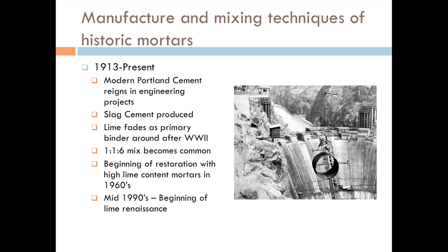So as we started moving forward, Portland cement, like I said, reigns in engineering projects. That's a photograph of the Hoover Dam. There's so much cement that was being poured in a day. Cement actually releases energy. It heats up quite a bit. And in order to slow it down, they would add pozzolans to it, because the pozzolans would consume some of the heat. It takes away some of the hydration. The heat of hydration would be slowed.